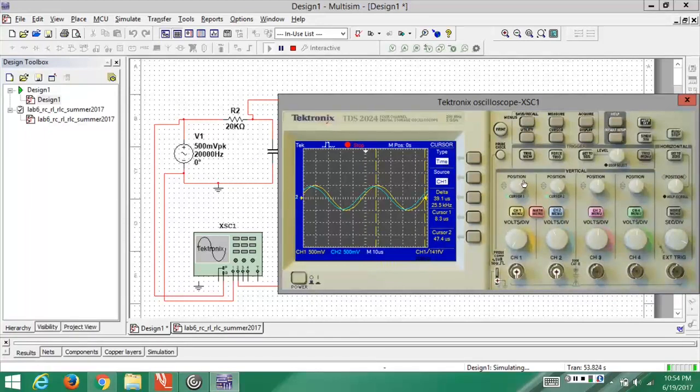You can either use the peak of the waveforms to measure the difference, or you can measure from the point where they intersect with the x-axis, whichever is easier to locate or identify.